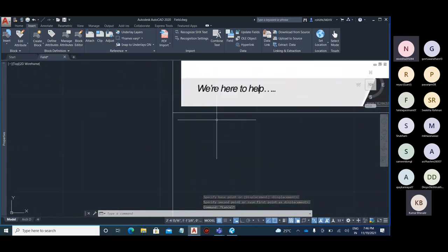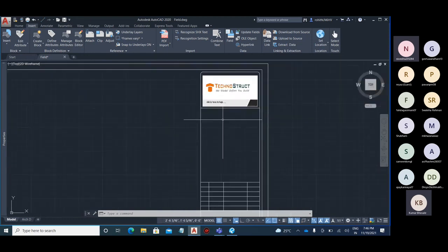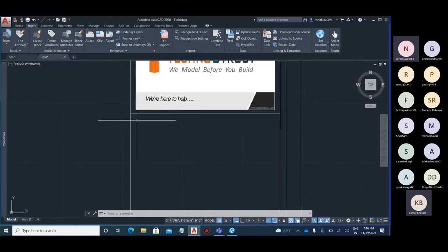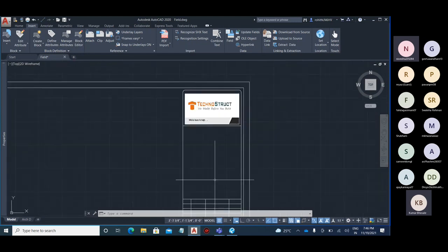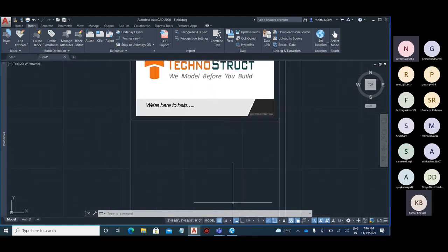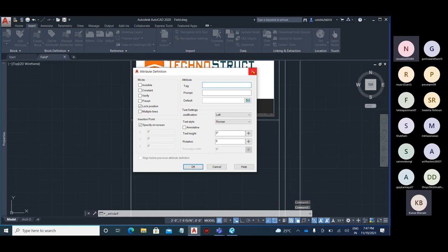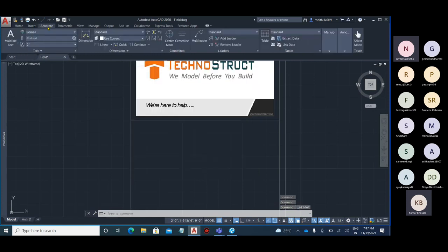Over here general notes is going to be there. So general notes can change from sheet to sheet. Okay, it is not going to remain same throughout all the sheets. So I'll just type over here text general notes, but whatever the thing inside that is there, that I'm not going to type, and I'm not going to create it as an attribute also. I'll tell you why not to create this as an attribute. What are the problems in the attribute, that also I'll tell you. So over here I'll say define, no need of attributes. Right now I am going to create a text.